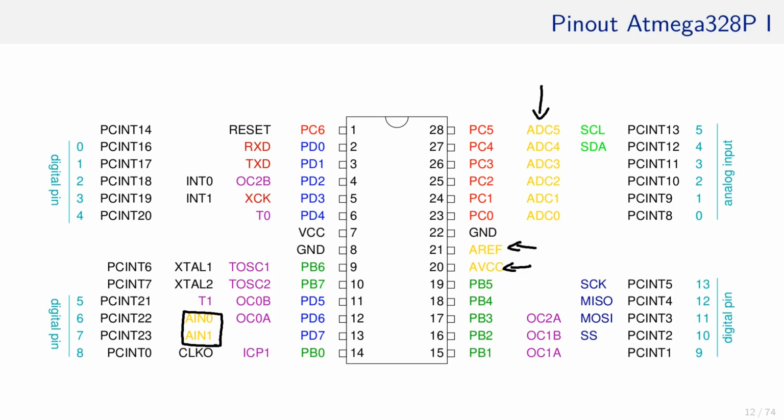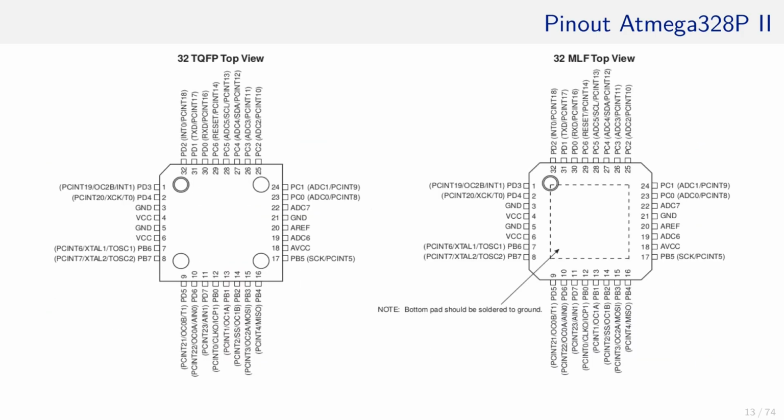As you can see, port C has only 6 pins. However, earlier I mentioned ADC6 and ADC7. Where are the other 2 pins? If you need all 8 connectors, also called channels, to the ADC, then we cannot use the 28 DIP that the ATmega is usually packaged in for the Arduino.